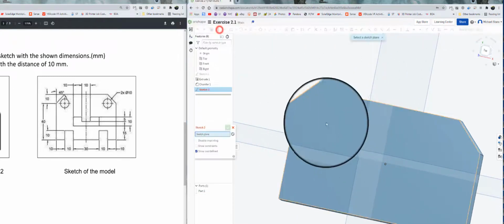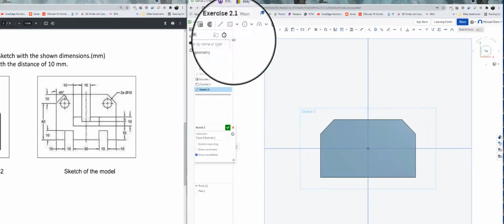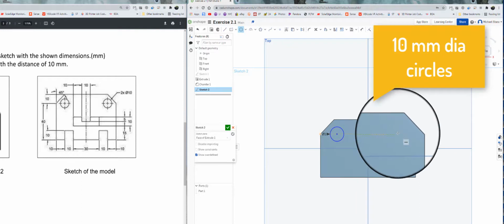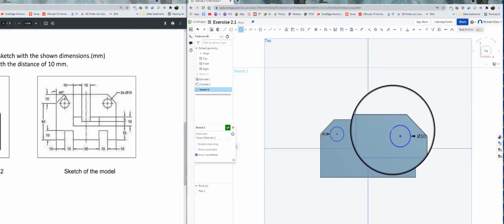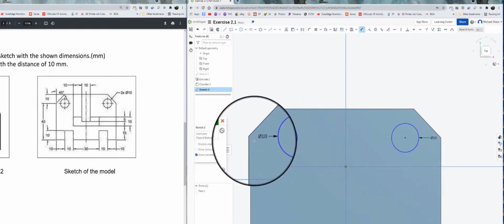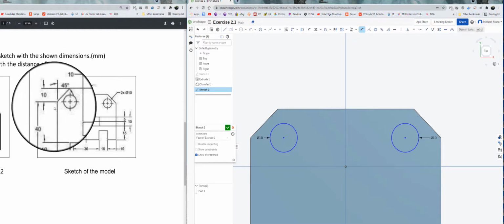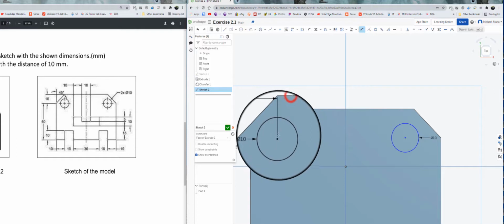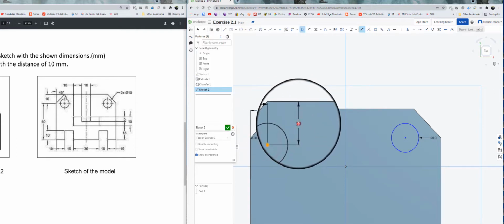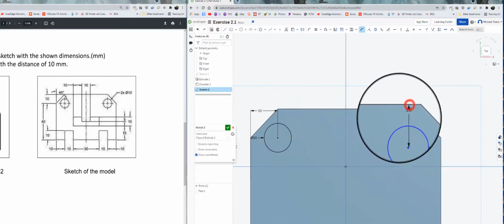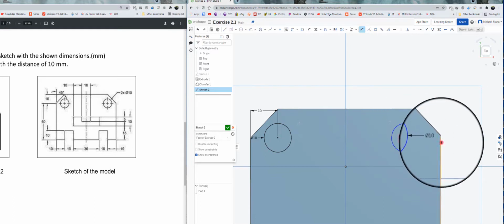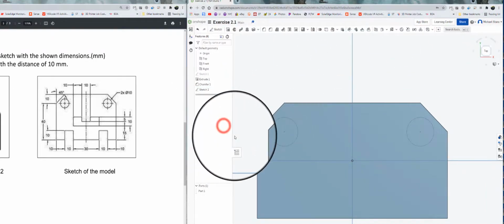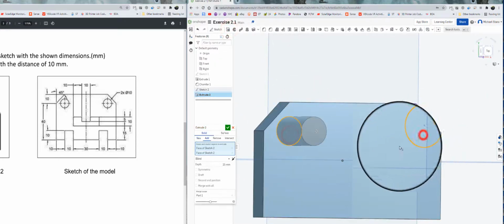Let's add those little eyeballs in. Okay, those circles are 10. Hit D for dimension. They are, looks like, maybe 10 in from the side. That's good. Okay, so now those are dimensioned. Could have actually mirrored those apart. That's fine. Okay, remove.